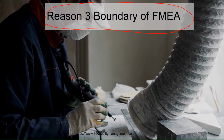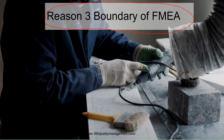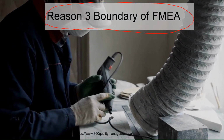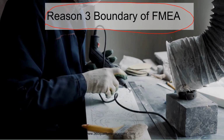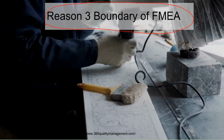Since FMEA is done by only one or two persons, usually a junior engineer, sometimes the boundary is quite narrow and focuses on what is deemed as risk from a very small group and from a very surface view of the process itself.